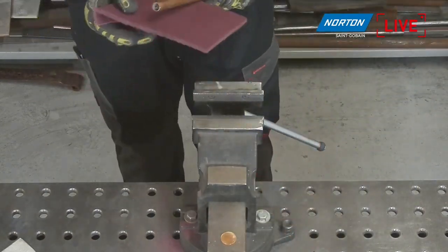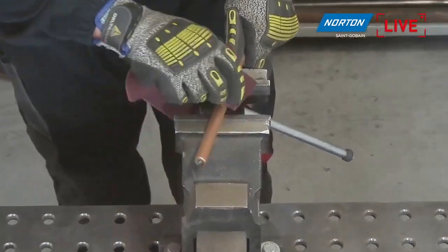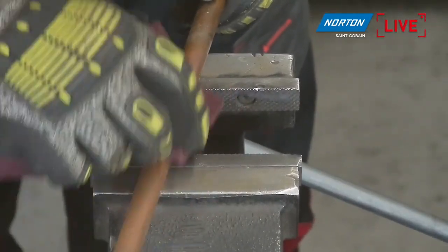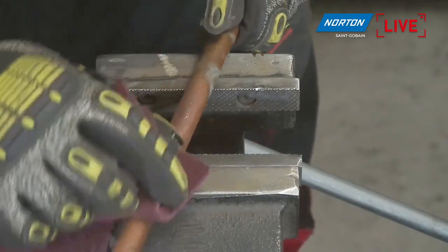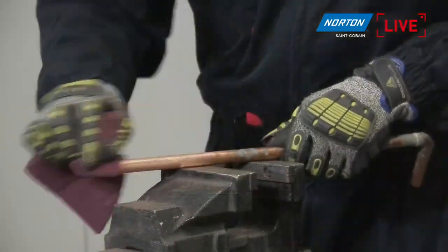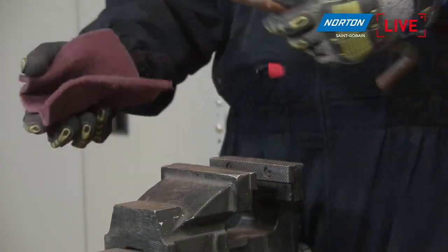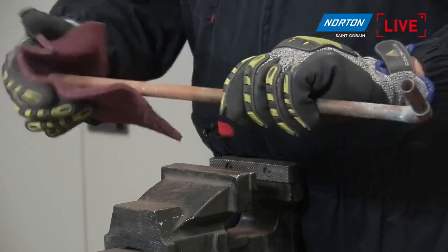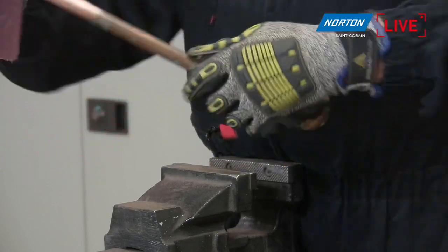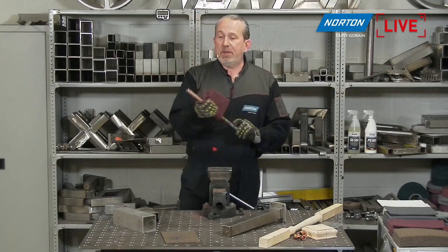With a very fine pad, very, very quickly, we can take that finish away to a very nice bright finish again, just like when you bought the copper from the DIY store, from the plumbing centre. So you can see really, really quickly we can clean that copper up. And any of you plumbers out there that do use this copper rather than plastic and push fit these days, you can see what an advantage this would be over the traditional wire wool where you'd use to clean up the end of this copper pipe before you actually do a soldered joint. So again, really quickly to finish that, and you see a lot of applications where people actually have copper pipe on show these days rather than burying them in the wall.